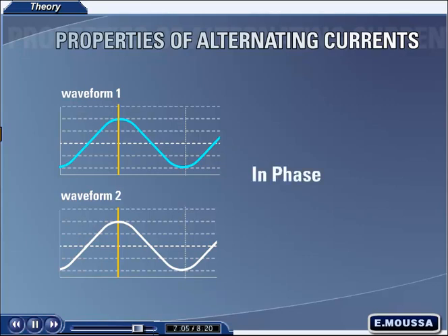We observed that by taking the peak of the waveform and the sine of the angle of the waveform at the same moment in time and multiplying them, we could calculate the instantaneous amplitude of the waveform. Therefore, these 2 waveforms could also be described as having a 0-degree phase shift with respect to each other, or there is no time delay between each waveform reaching the same point in their cycle. Note that we can only describe the phase shift between waveforms of the same frequency.